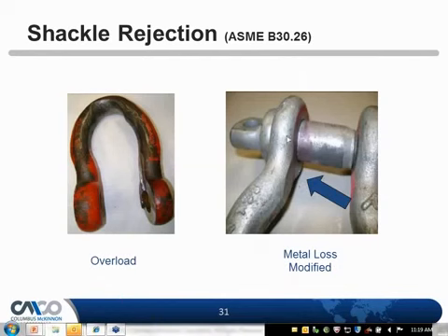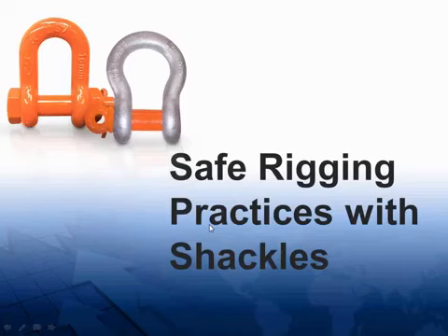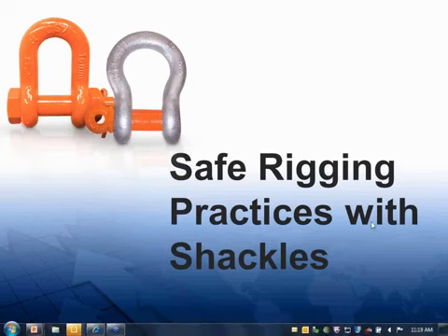Again, just certain things we found: grinding and wear over here, the shackle off to the left, overload, just extreme deformation there. Get it out of service. Anytime you suspect you overloaded it, or someone has overloaded it, take it out of service.